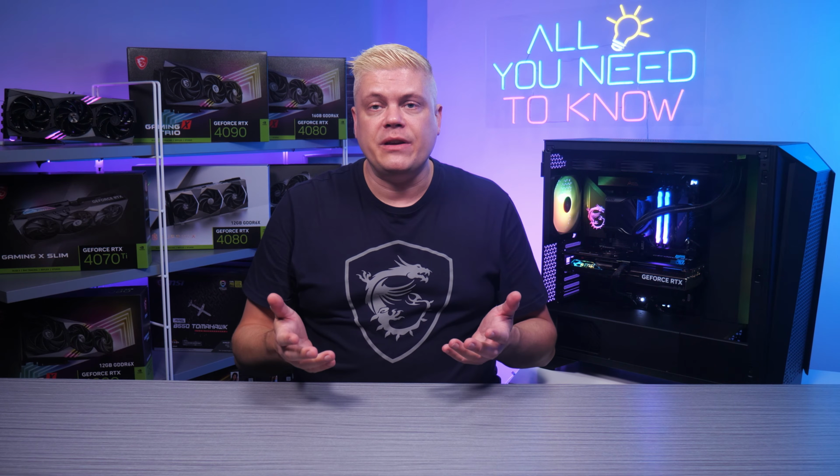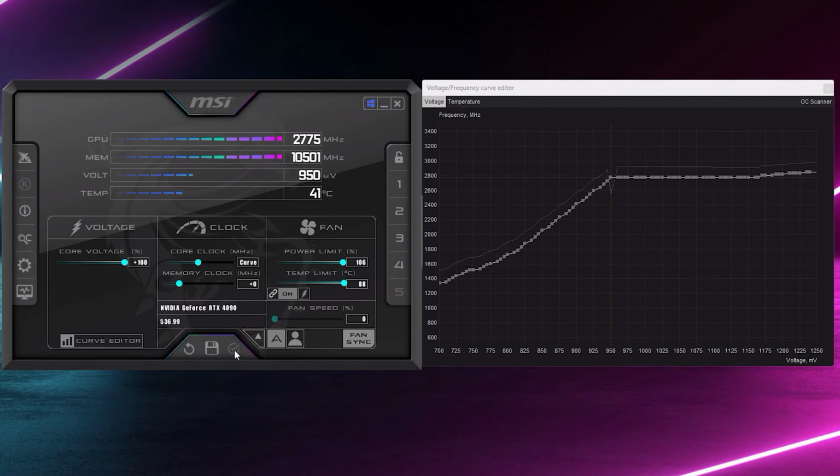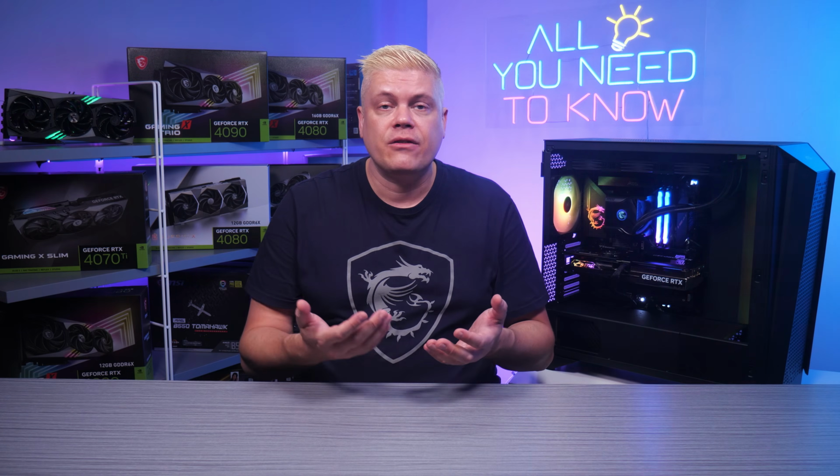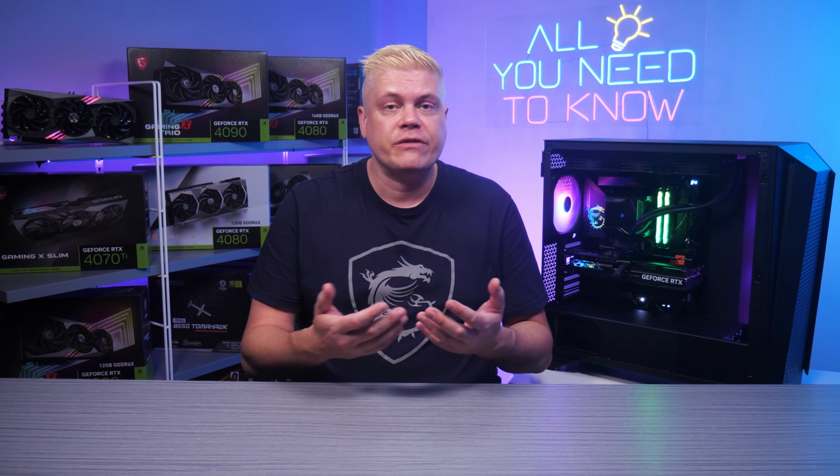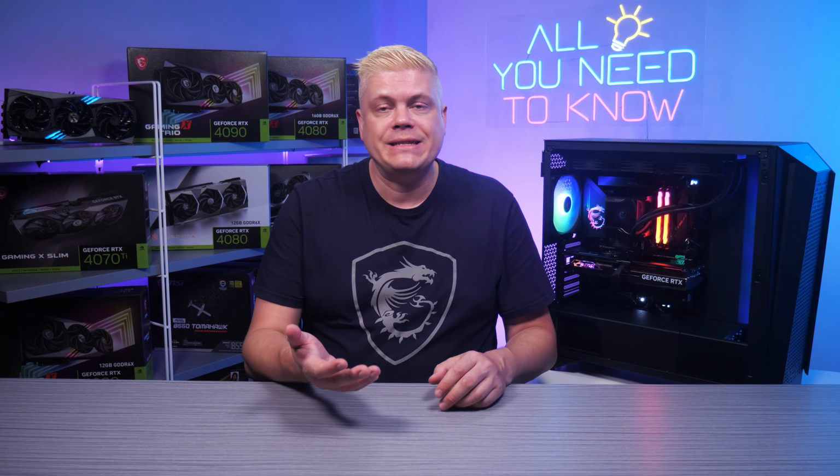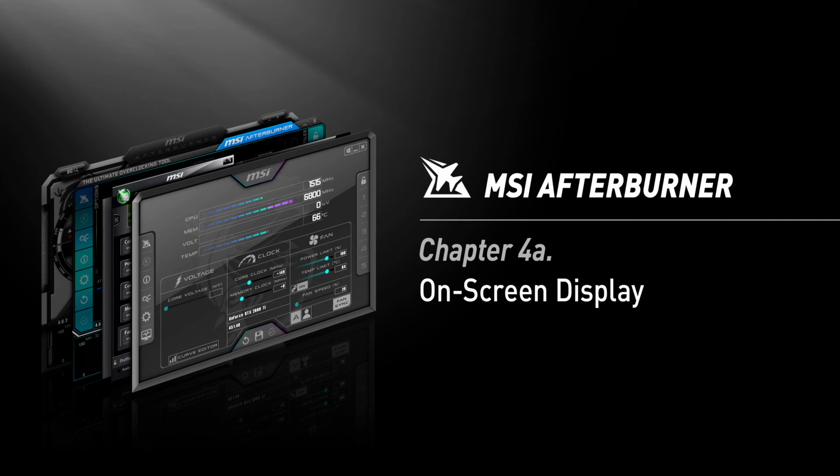So why aren't all GPUs undervolted by default? Manufacturers pick stable settings that run all GPUs at a certain tier, as even identically made GPUs can have slightly different voltage tolerances. With undervolting, you could see less FPS, greater and more 1% lows, or screen tearing and instability, though you can reset to fix any changes you've made.